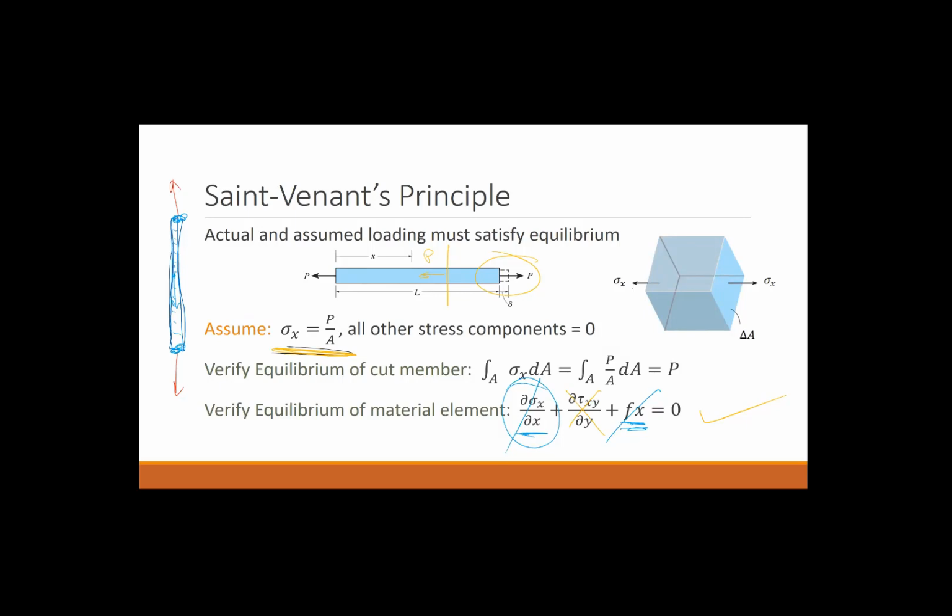And the normal stress is your P over A plus some linear function of X that goes from 0 at the bottom to the full value of the weight at the top. And then when you take the partial derivative of that, you end up with a value that is equal to your Fx force. And then, well, it's going to be the negative of it, so they're going to negate each other.